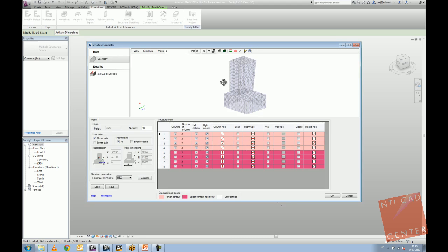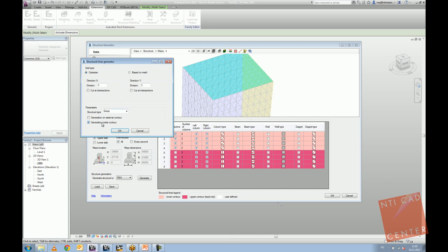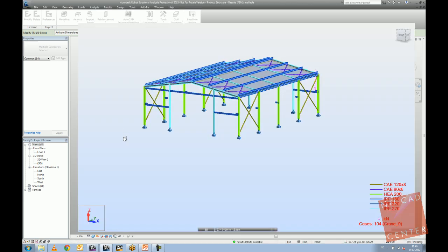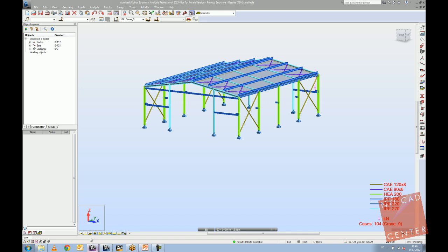You will see that the model was interpreted here, where basically I can select the structure as a separate element. So let's say selection. For example, select this roof. When the roof is selected, you can generate the structural elements. Let's try based on model.